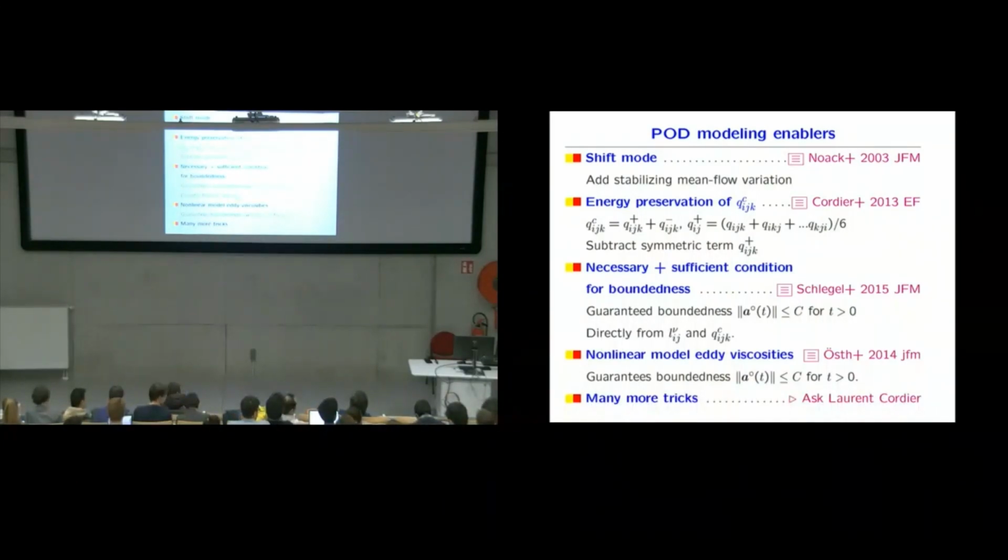Good question. We've written one paper where we showed 4 different definitions of the shift mode. For instance, you can say it's the difference between the steady solution and the mean flow. You can say the shift mode is the one which you derive from the Reynolds equation. Essentially, you look at the linearized Reynolds equation and look at the fluctuation. In which direction would you go based on the Reynolds stress?